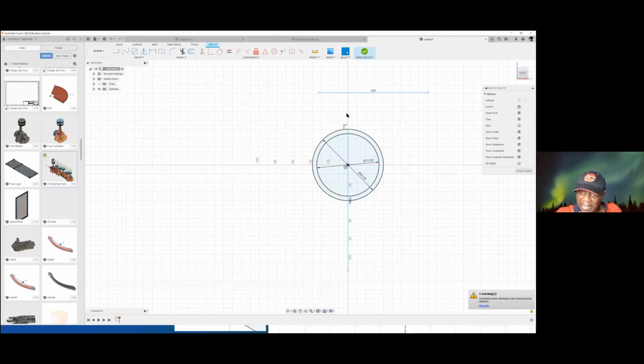Oh no, it's still not extended. No, I want it extended. Okay, and then I can trim that thing that I had there. So you can see this line is a vertical line that goes all through. So I can choose that line and turn it into a construction line. Oh no, undo. I want to undo the trim. So I can turn that line into a construction line by choosing it and pressing X. So that whole line is now a construction line.